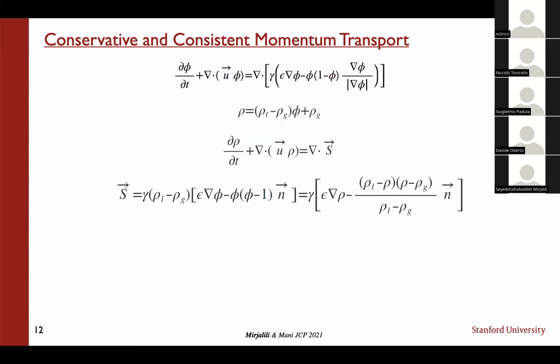The other thing is, I agree with you in terms of CFL conditions. The CFL in 1D is 0.5, in 2D it's 0.25, and in 3D it's about 0.33, so with every dimension you get a penalty, and it is not great. That is why I'm very interested in implicit treatment of this phase field model, but we haven't succeeded so far because of a nonlinearity. So we are looking at semi-implicit schemes, but I don't have something concrete right now.